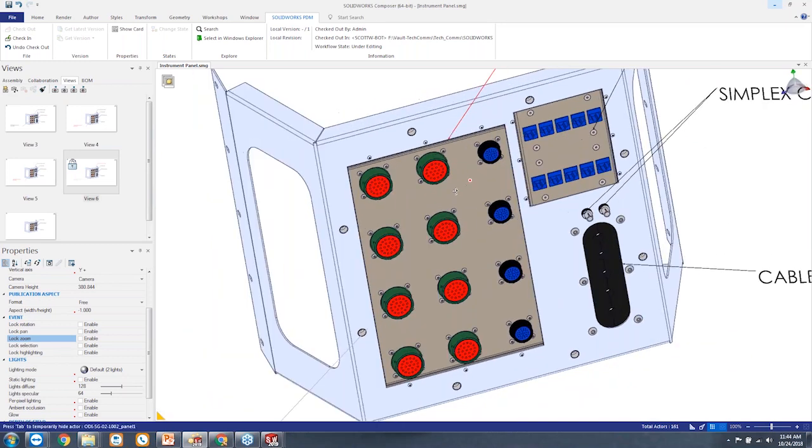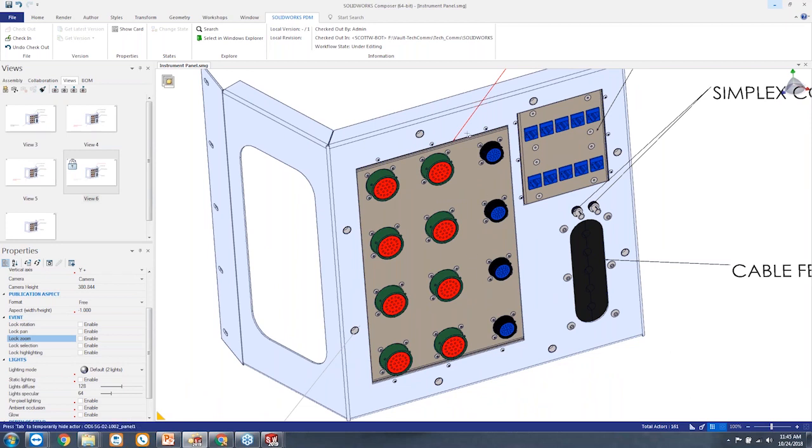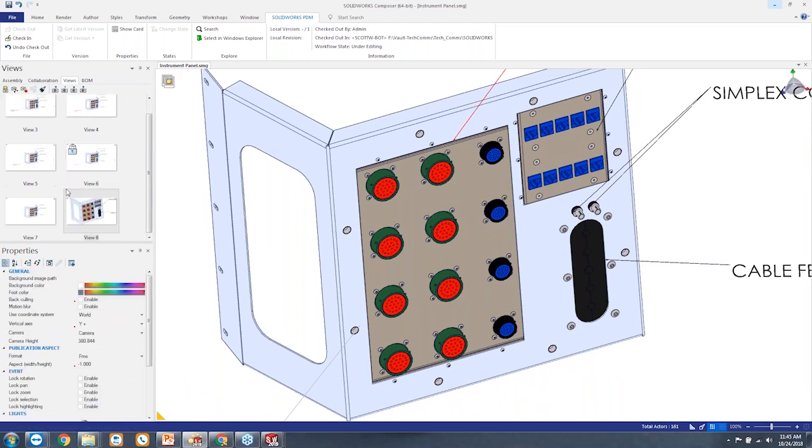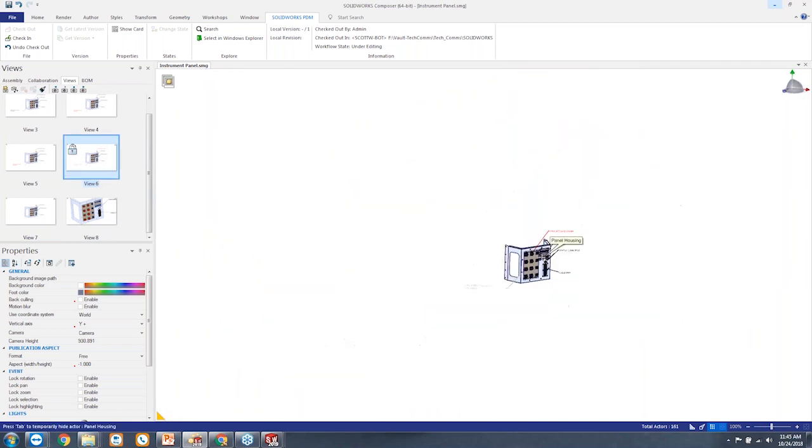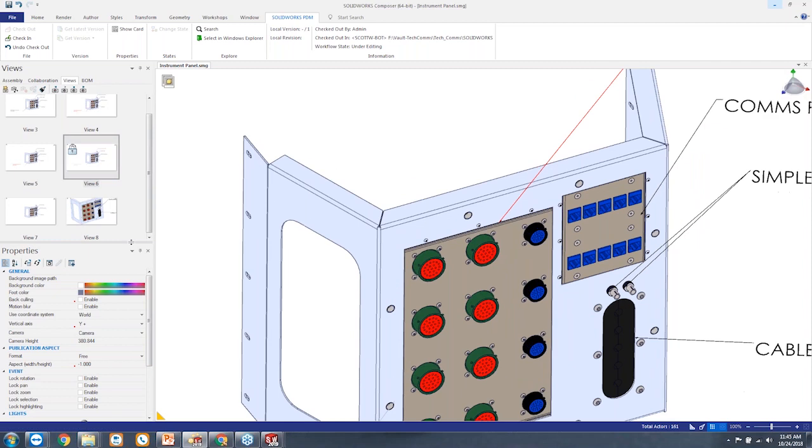And if it was locked, I wouldn't be able to do that. And so right now I can zoom in, I can change something, I can create a new view. But what I can't do is update this one that has a lock on it. See, update has been disabled. I can update this one, but this one I can't. So really, you can come through and it looks like you can adjust it, but you can't actually change it. Anything you change, you have to either discard or create a new view of.